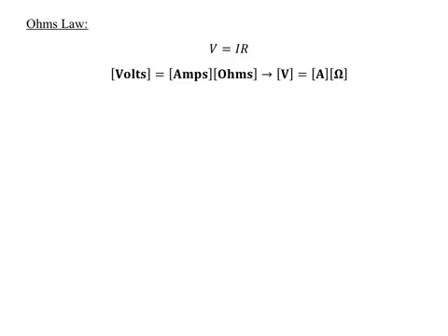In electrical circuits, the idea is that the resistance of something is usually determined, and it's a property of something. So for the most part, a lot of people solve for R, and they say R is the ratio of V to I. So if you have a material and you want to determine its electrical resistance, how much resistance it has to the flow in the circuit, you can apply a voltage to it and measure the current. Or you can apply a known current, if you know the current going through it, and measure the voltage drop. And we're going to do that in this class.